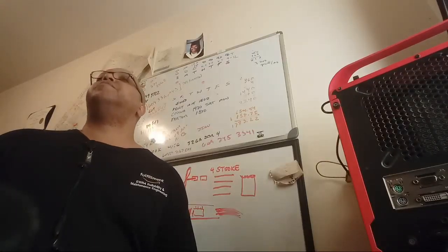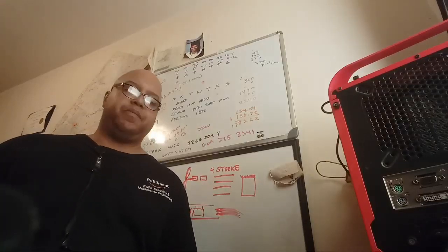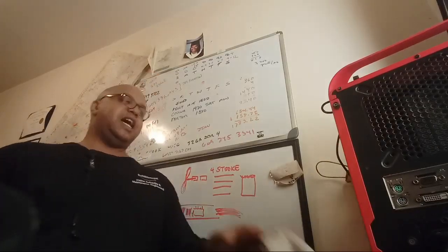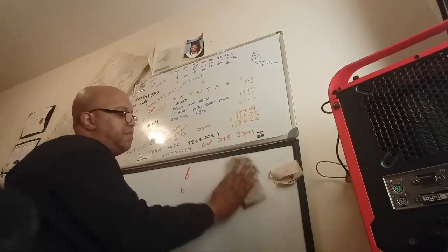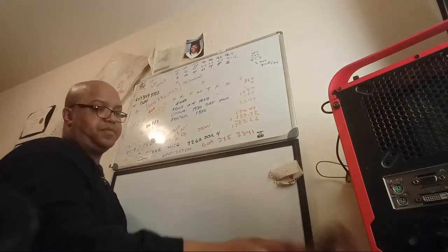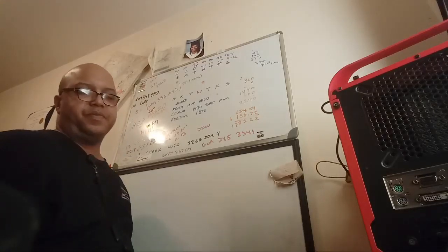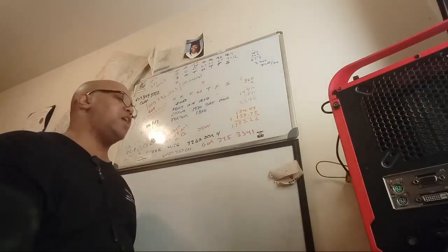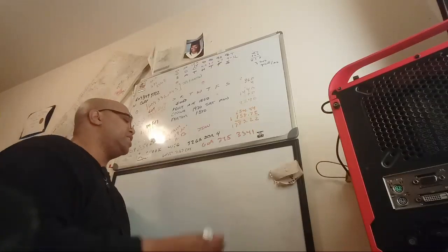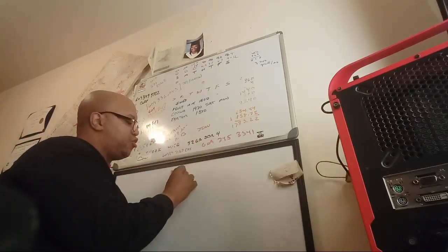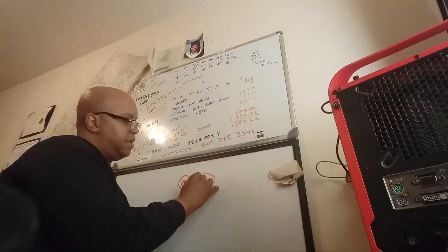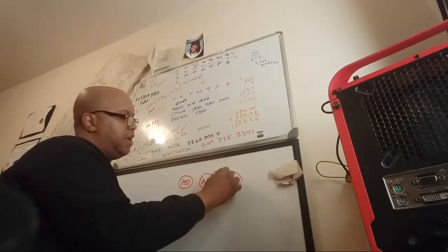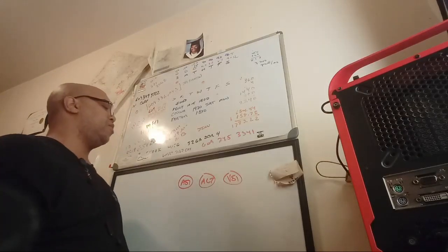All right. The Pitot static system. Any idea what that is, the Pitot static system? That is what helps measure your airspeed indicator. Okay, it's part of it. You have three instruments: airspeed indicator, altimeter, and VSI, your vertical speed indicator.